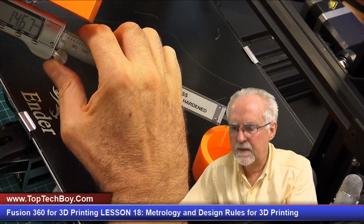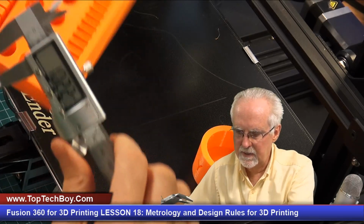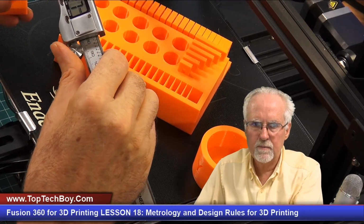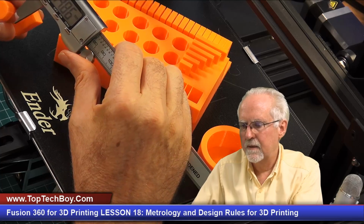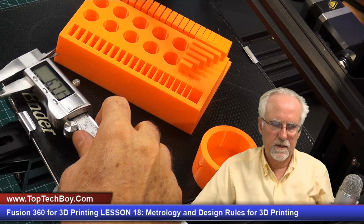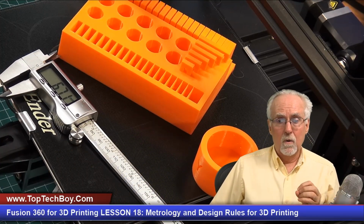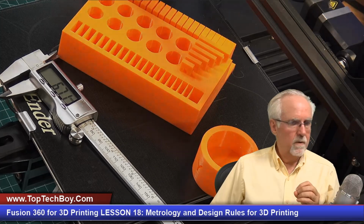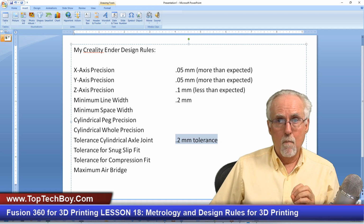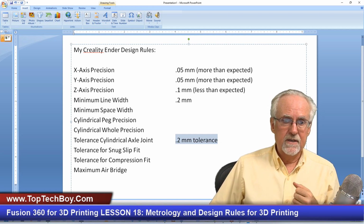And it is coming in at 14.8. All right, it's coming in at 14.8. So the hole is smaller than what we expected, and the pin is smaller than what we expected. But if we leave the hole 0.2 millimeters more than the cylinder, it fits nicely.